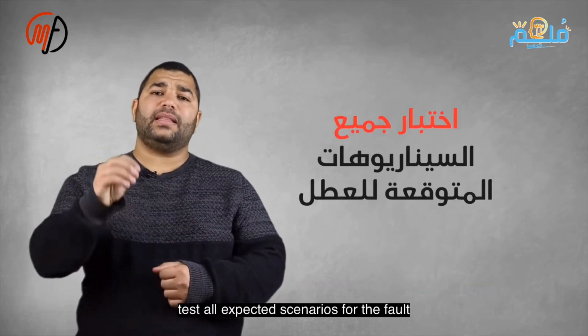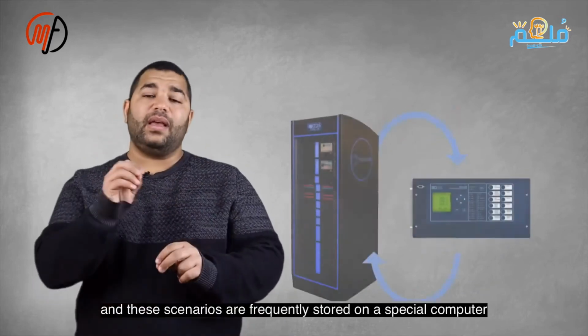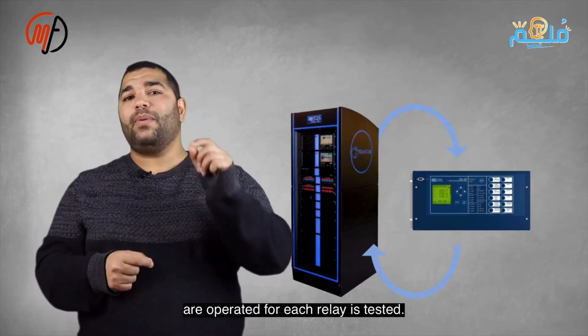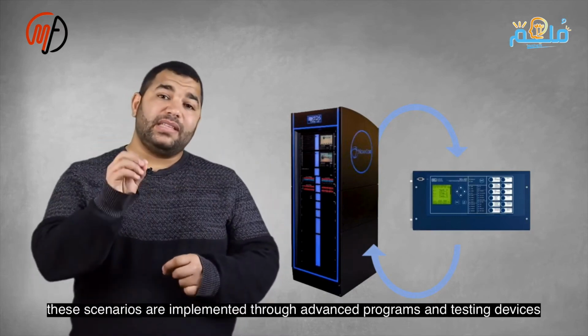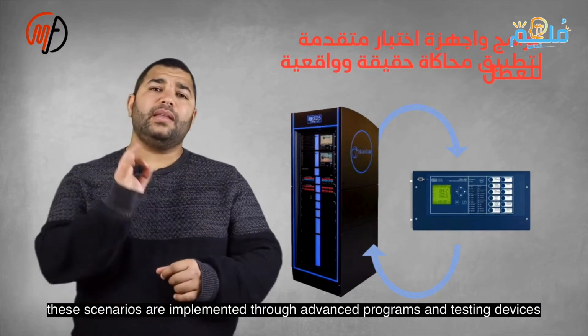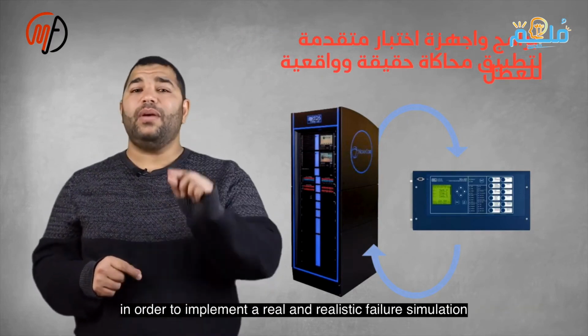For instance, a relay may need to trip at a fault after 9 milliseconds, but if it trips after 50 milliseconds, it is rejected. Only one relay is tested at a time, and approval is for the version that underwent type testing. For example, a Siemens relay, model 7SD version 4.6, if type tested, is approved. Newer versions are prohibited until retested.